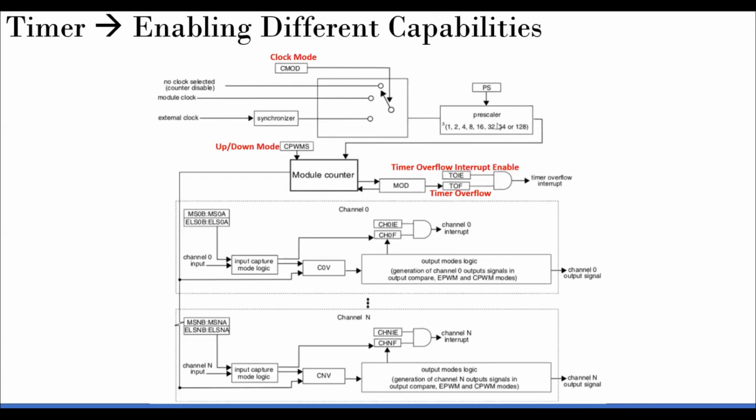And then you have a prescaler option. So you can prescale this value as I was showing you in the previous slide. And there is a register where you can select 1, 2, 4, 8 up to 128.